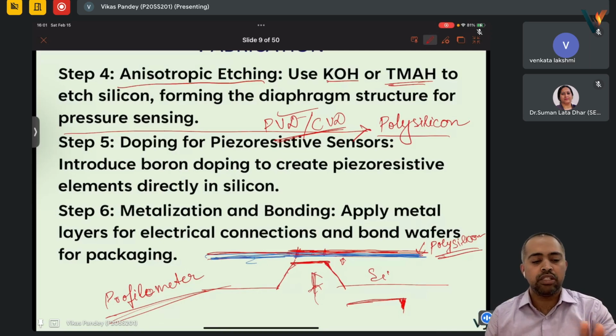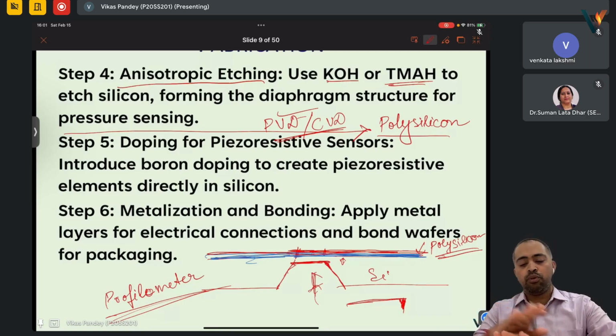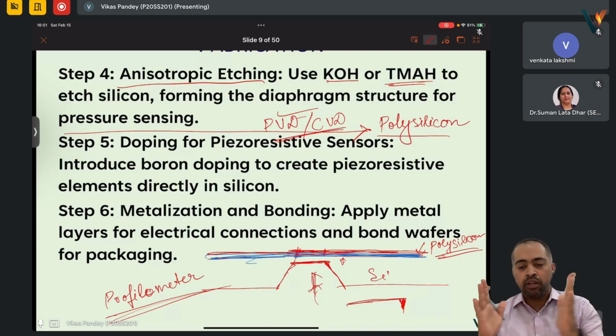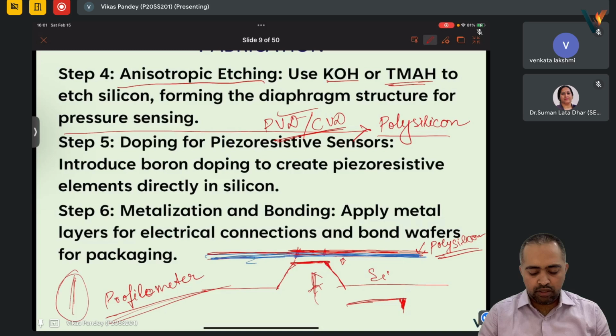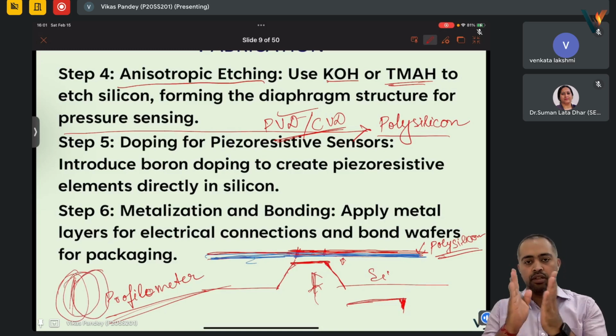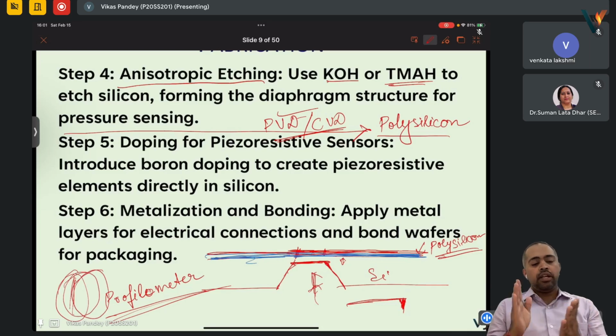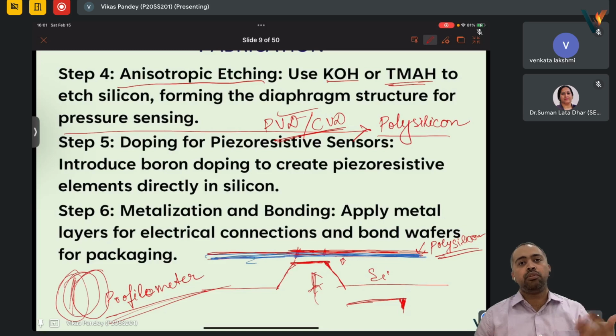There are some ways where one boron wafer will be kept between two silicon wafers, in a sandwich kind of structure, and then boron will pass as we put it at higher temperature. There are other processes, very similar to chemical vapor deposition, where we use some precursors. Generally, when we are putting phosphine gas for phosphorus, we will see phosphosilicate glass forming on the other side. These things are there.